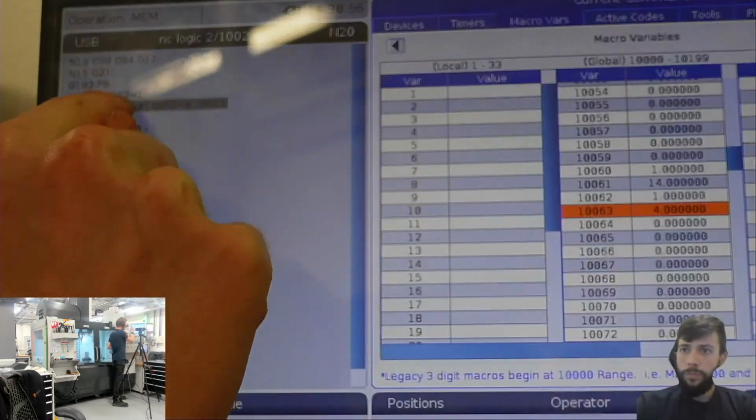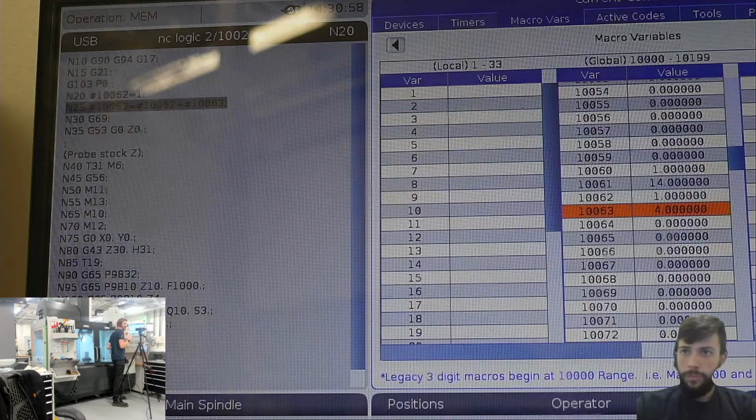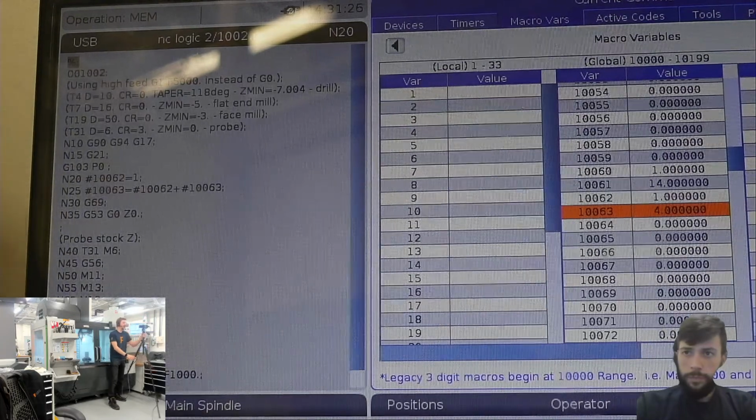It's reading lines ahead of time and filling in the data. Now that can cause really bad problems if you're using the same hash variable for something twice, because it could have overwritten the value before you expect it to. So that's something to be aware of when you're doing macro programming, is to make sure that when the machine looks ahead, it doesn't start overwriting those macro variables for you. So right, hope people are understanding how we are getting on at the moment.